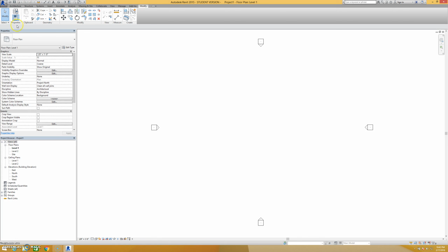Okay, down below your toolbars, there's this area which will pop up as green at different times, and it basically gives you further options for the commands. So we'll look at that as we go through several different commands because there'll be options here. For instance, if you do the copy command, generally speaking, if you have anything you can copy, it'll show whether or not you want to copy multiple things. If you have the mirror command, something will show up here that'll allow you to copy or not copy when you mirror.